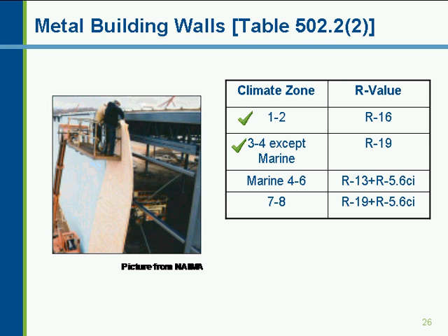There's a way of trading this off using a tool like ComCheck, for example. You might be able to trade off the foam board insulation and just have mass wall with the insulation installed between the framing versus having the insulation between the framing and the foam board insulation. I haven't seen too many installations where you put in both foam board and insulation between the framing when furring out on a mass wall system. So that's a good opportunity to do a trade-off using a tool like ComCheck.